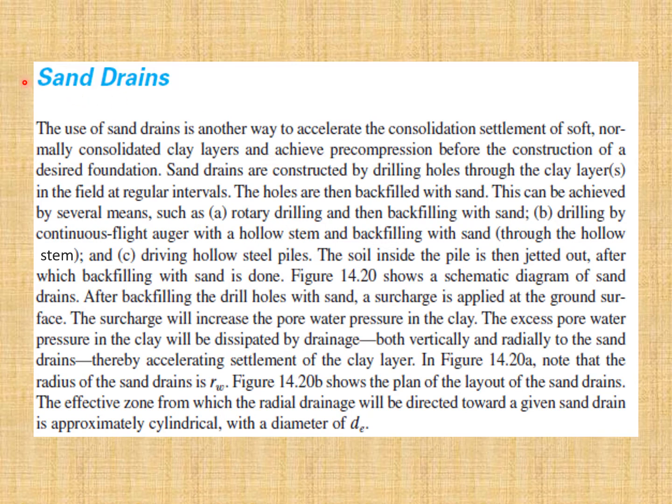Now come to the topic of sand drains. The use of sand drains is another way to accelerate the consolidation settlement of soft, normally consolidated clay layers and achieve pre-compression before the construction of our desired foundation. Sand drains are constructed by drilling holes through the clay layers in the field at regular intervals. The holes are then backfilled with sand.